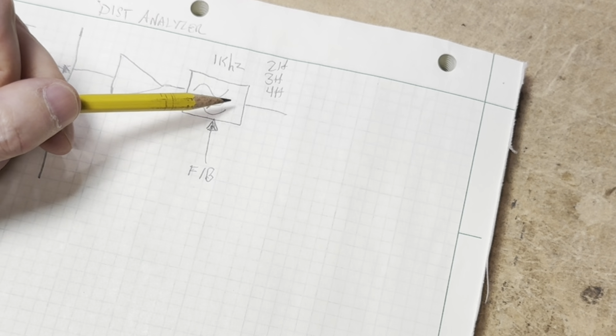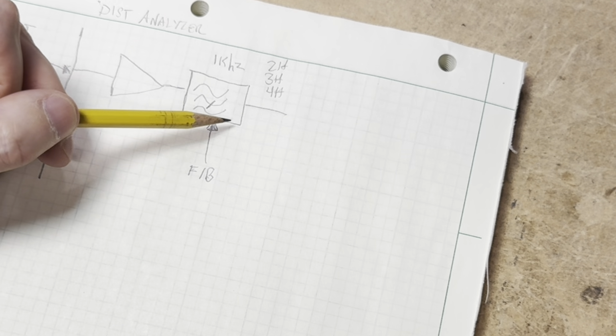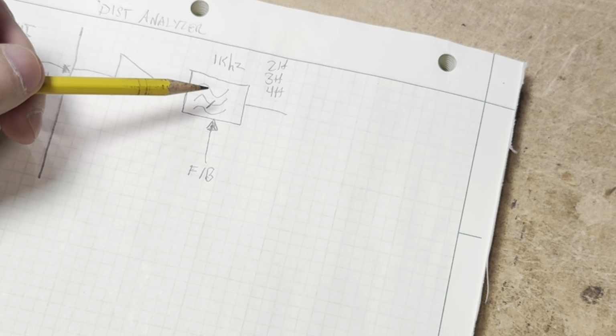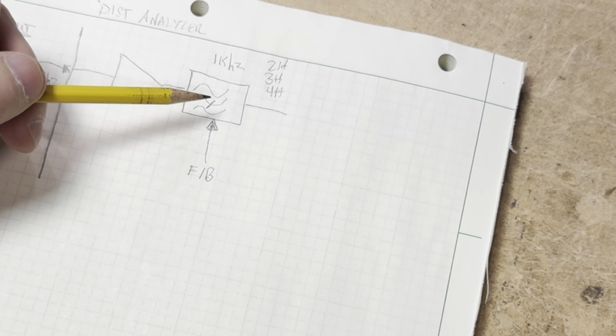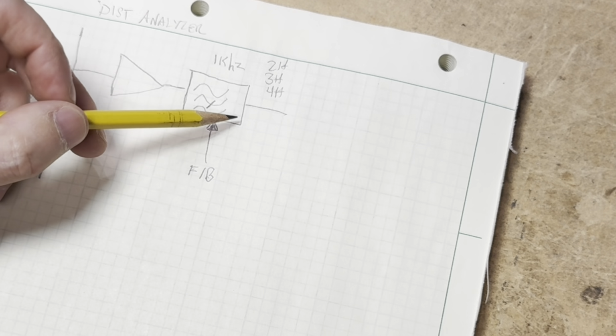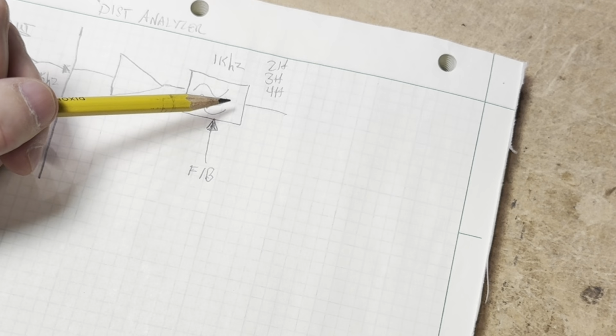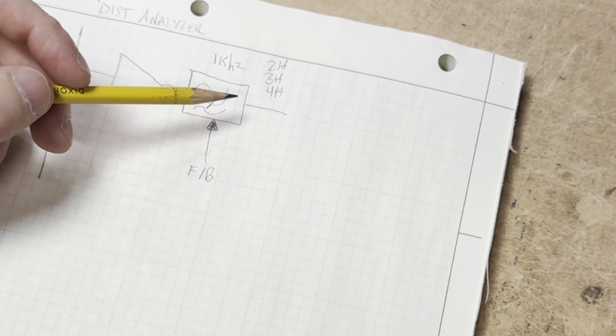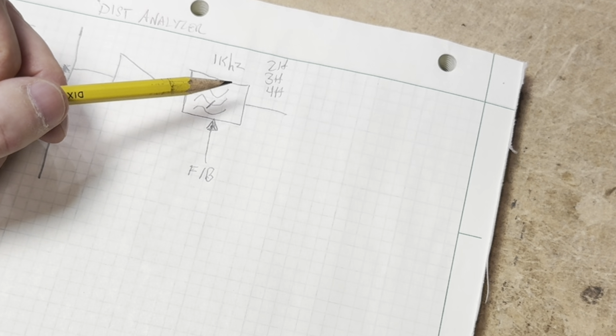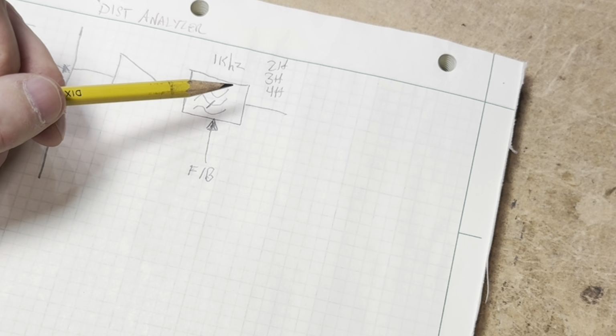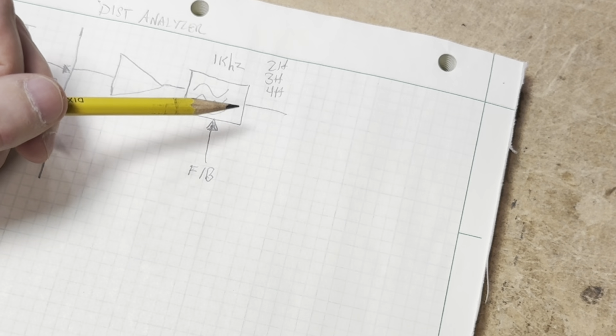This is probably the most complex part of your distortion analyzer system, getting the notch filter system to work and the tuning of it, because it requires a great deal of switching, especially when you're talking about covering wide frequency ranges. The HP339A distortion measurement set has a great deal of switching involved.